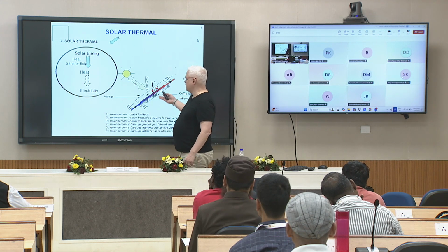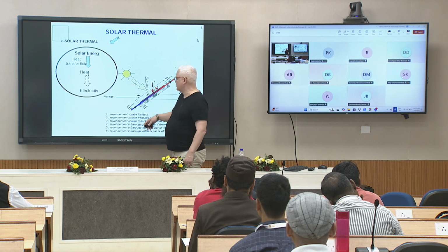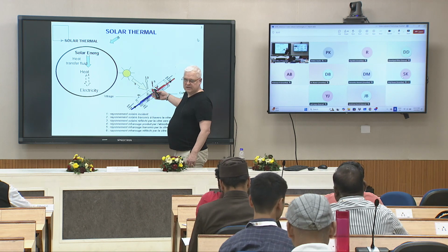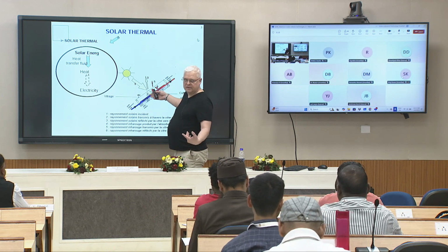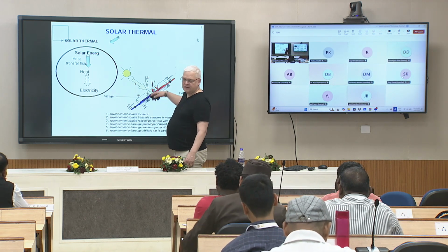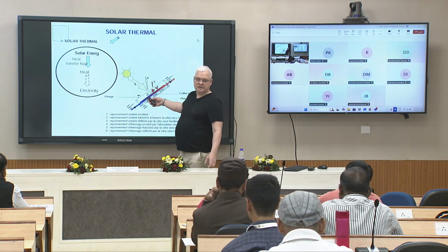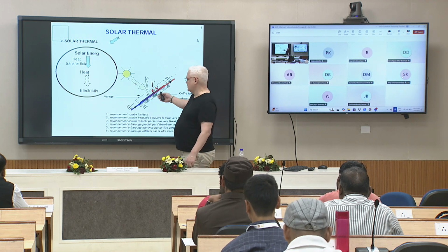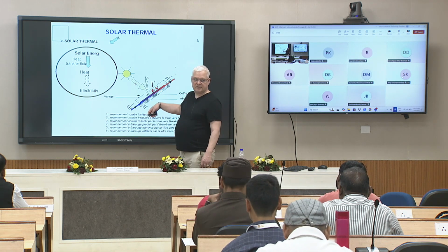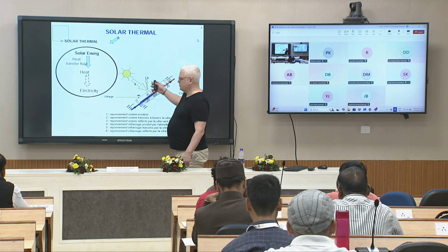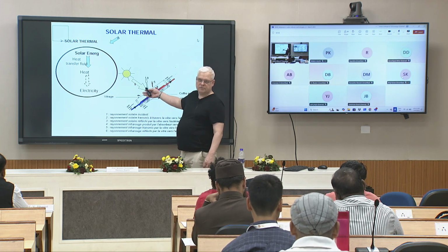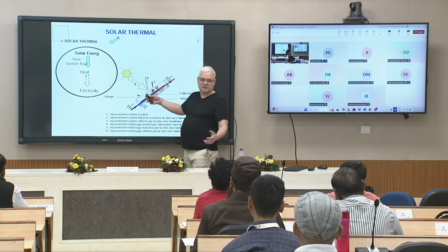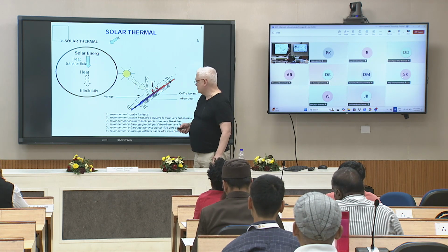The principle of a simple solar thermal collector is to have an absorber which is selective, very absorbing. At the back side, you have a fluid that could be air, water, oil, that is collecting this heat. Depending on what you put at the top of the absorber, you are losing more or less heat, or that allows to increase it.